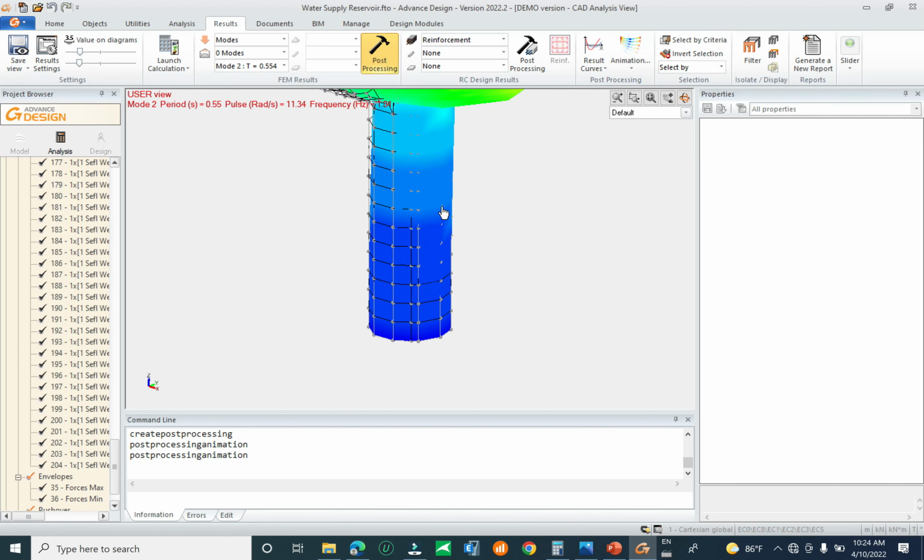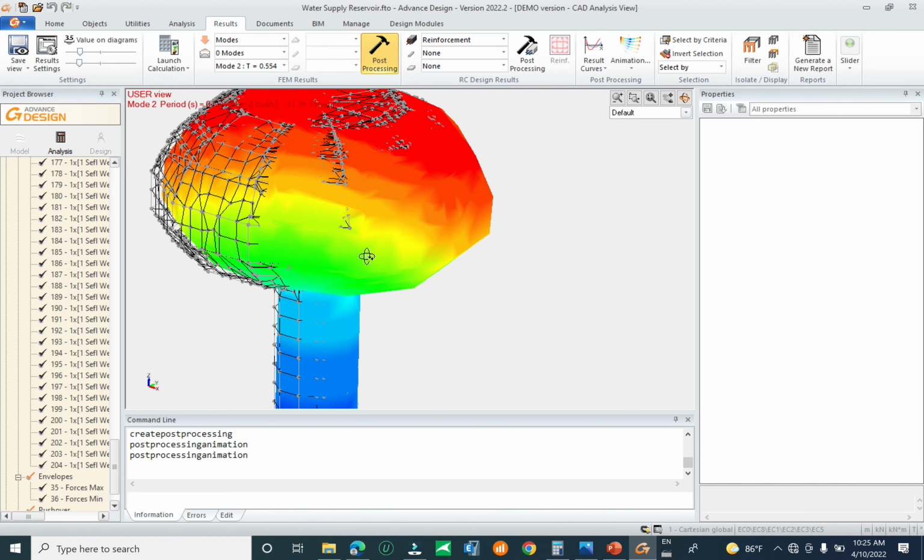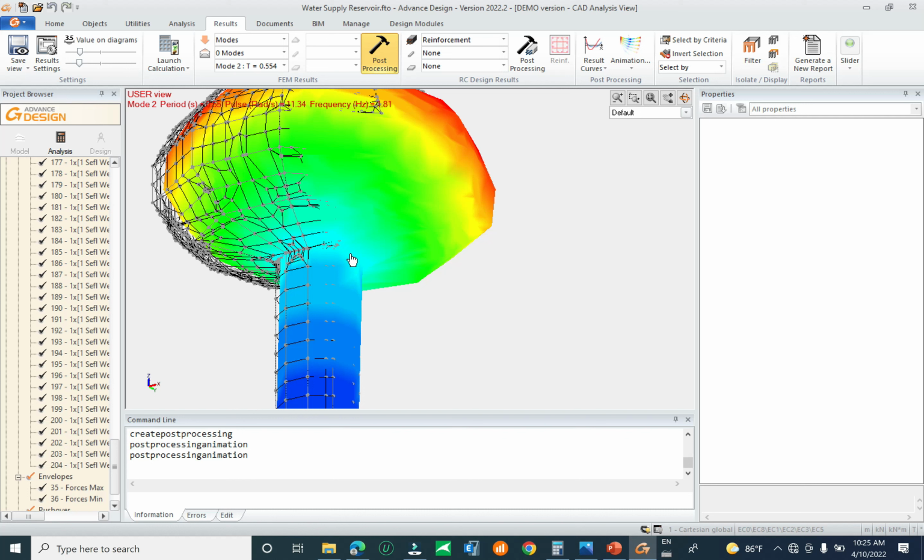You can add under cell or under flat to restrain at the middle span, the middle of the vertical wall. And for the top of the wall you can add another beam to improve the deflection. You see here the deflection in the area is too much.